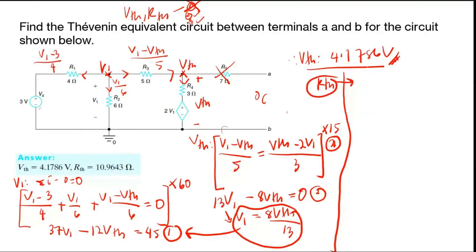Okay. So to find the RTH, if you're using the second method, it means that you add the test voltage or test current, which is V node or I node, both equal to 1. And then you can turn off the independent source. Okay. You can turn off the independent source. So you can just do these two things if you are using the second method.